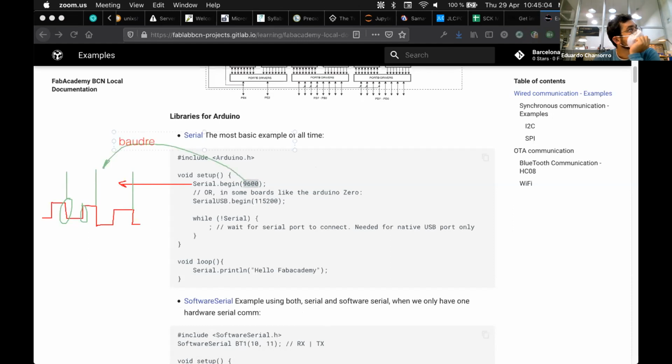If you set the baud rate in the serial monitor wrong, lower than the actual one, the signal you see will be garbage data. You just get garbage because you are expecting data at a different rate.